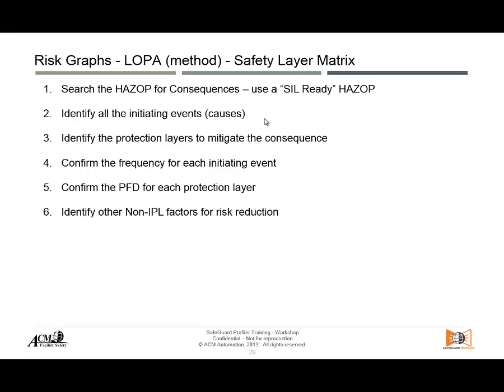They would be, for example, process safety valves, or they could be other trips coming from the basic process control system, coming from a PLC, coming from an independent sensor and actuator, from other places that are not really safety implemented functions. And that's what we call all the other safeguards, right? So we identify those other safeguards that are not safety implemented functions. Identify where more precise numbers are required.